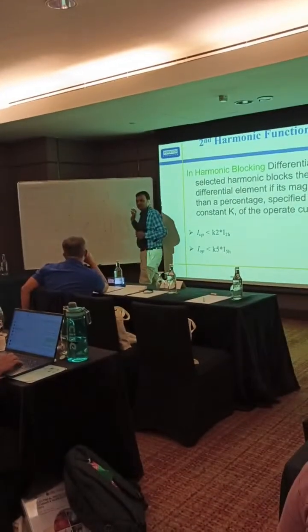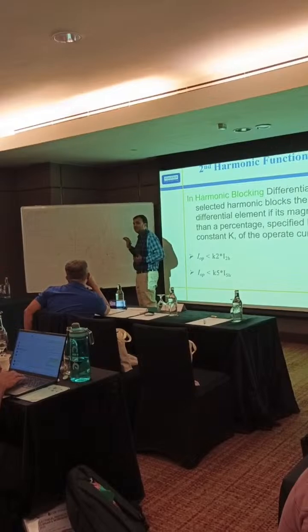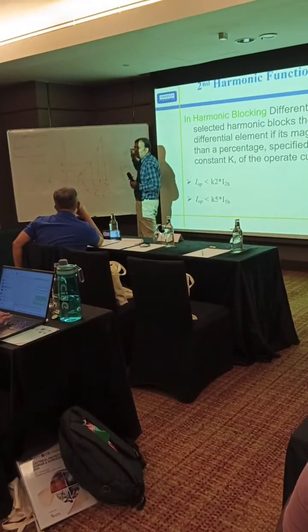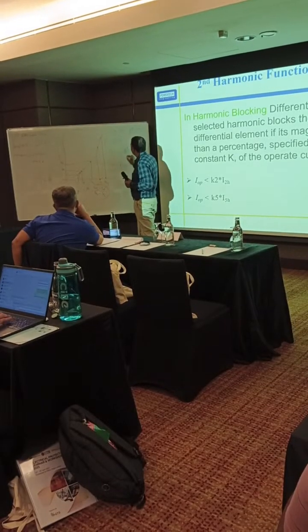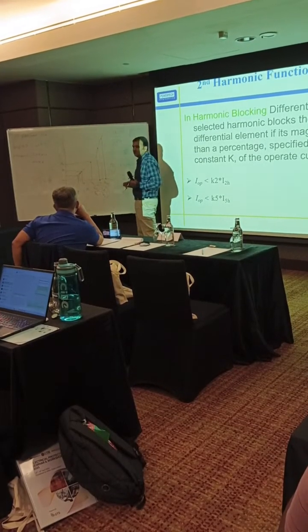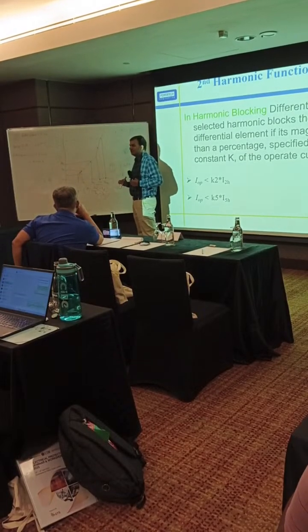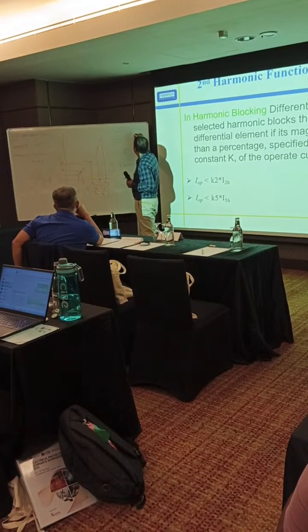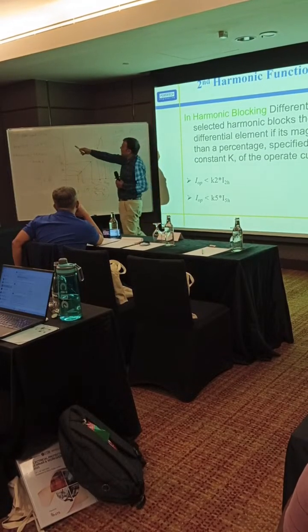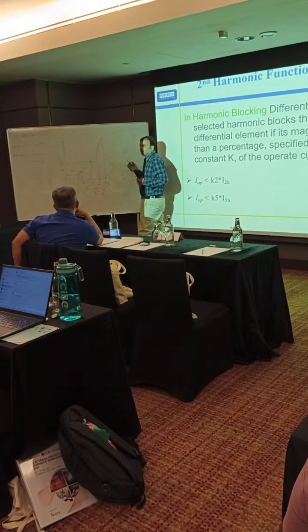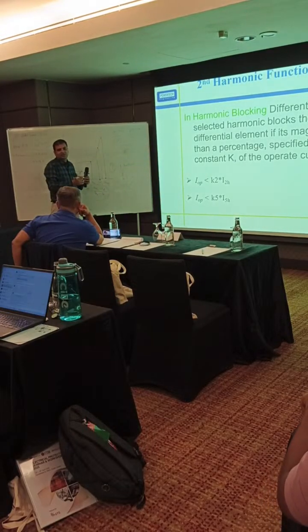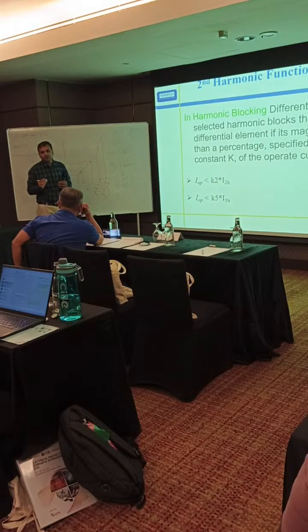No, no. I just want this harmonic component, not adding all these things. So how much current will it take? Why 1? It will block because our setting is 20%. So the 20% of what? Fundamental current. It is not like that every time it will trip at 0.2.